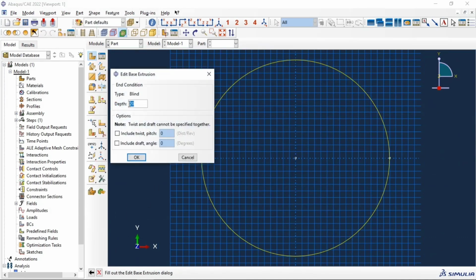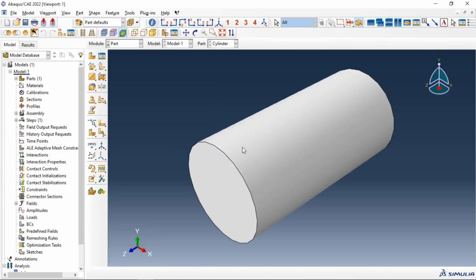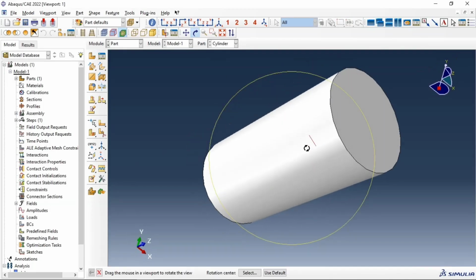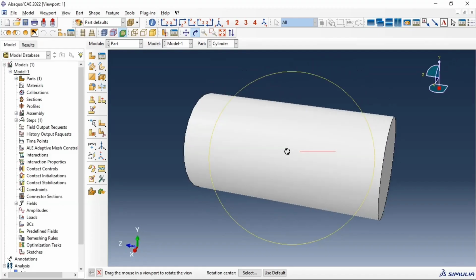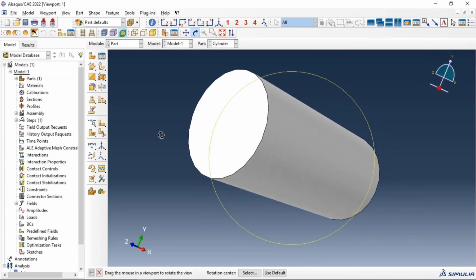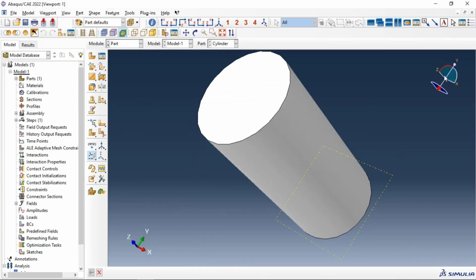So we'll start by creating the specimen. Create a new mechanical scenario and begin with the new part. The specimen used here is a standard concrete compression cylinder having a specific diameter and a specific height. Select cylinder from the primitive geometry tools, enter the required dimensions, and confirm the geometry. This cylindrical specimen now represents the concrete sample that will undergo axial compression. At this stage, the geometry is intentionally simple, allowing us to focus on the material behavior rather than the geometric complexity.